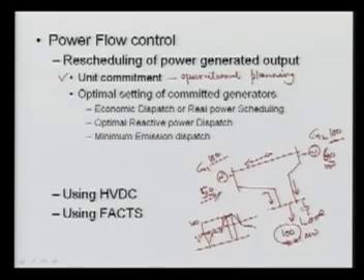So generator 1 is on here, generator 1 and generator 2 are both on here, and here generator 1 is on again and 2 is off. So generator 2 is on only for this period. This is called unit commitment. Still generator 1 is on, but again it is the loading, just how much we have to load.